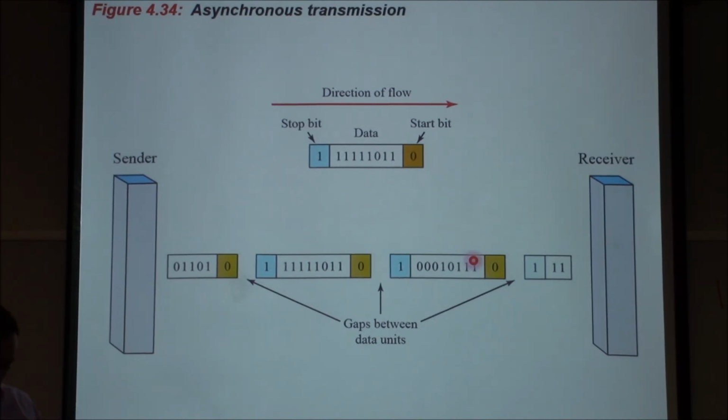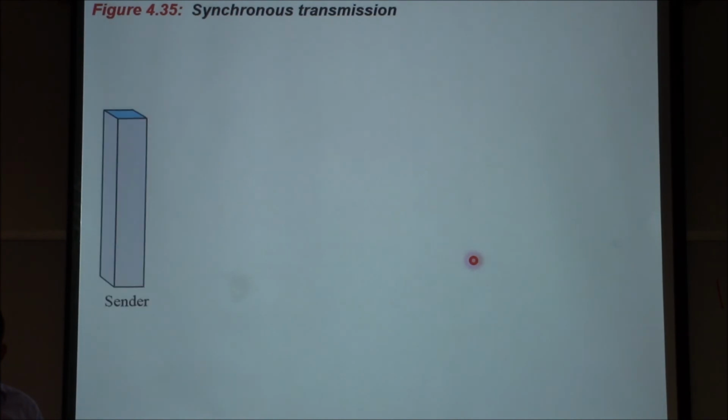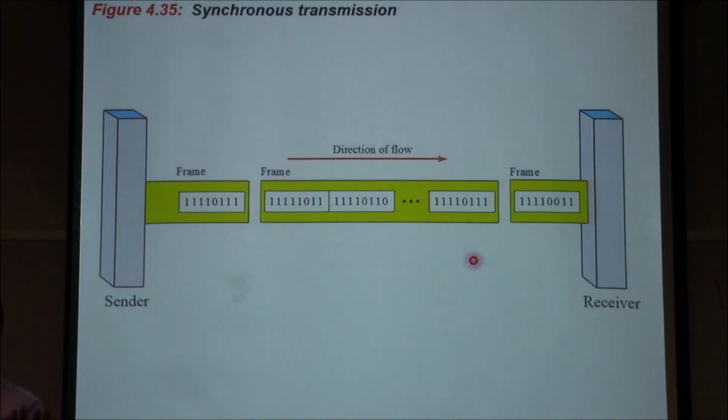For example, the keyboard that I have here, when I press on the keyboard, I am really sending only 8 bits, 1 byte, right? So that kind of asynchronous transmission can be used between the keyboard and the computer for limited low data rate applications. So for high data rate applications, which is what we have in the internet, we use synchronous transmission.